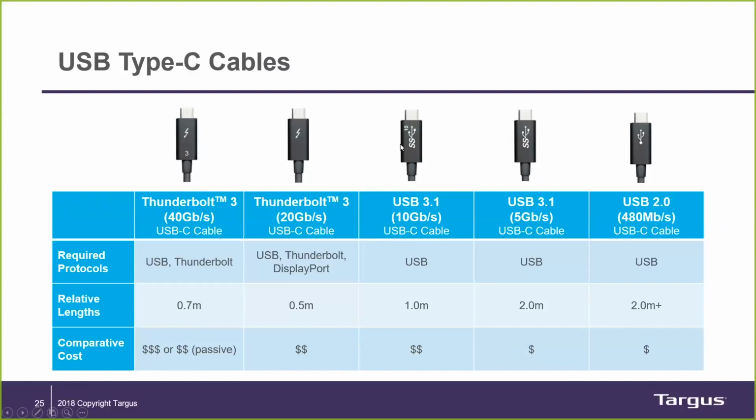These cables over here are wonderful, especially this one for alt mode and these for regular old USB, and you sometimes get away with them in alt mode, but you still want to use this for alt mode, and you definitely got to use this for Thunderbolt. That is to say, these cables will give you some functionality in Thunderbolt, but certainly won't give you the 40 gig Thunderbolt capability. So keep in mind the cable connection is important. While they may all look alike at the port connection, they should be logoed differently. These are the logos you want to look for.